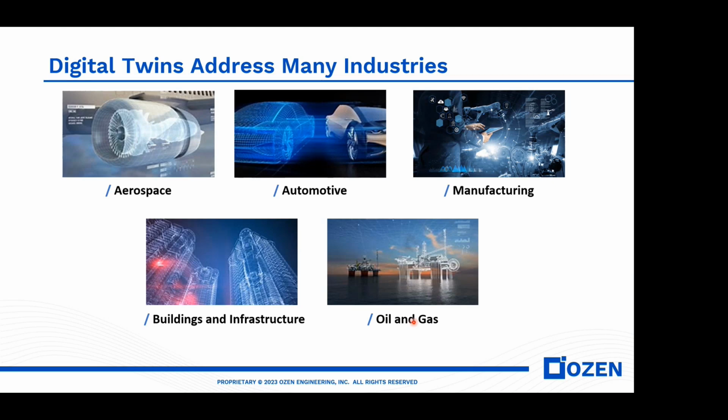And if a company has a twin model for these two engines, they will be able to understand which kind of wear is taking place in which engine based on where the engine is located. And that way, the maintenance schedule for these engines can be separately created. The parts and equipment required for the engine to be in operation as long as possible can be set up much more easily. So that is where the predictive power of digital twin helps.